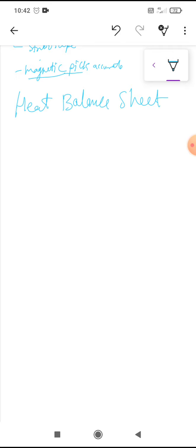The heat balance sheet represents an account of the heat supplied in the fuel and released in the combustion and its utilization in the engine. Necessary information concerning the performance of the engine is obtained from the heat balance sheet. In order to draw a heat balance sheet, a complete test on the engine must be carried out while the engine is run at a constant load. So, heat supplied.